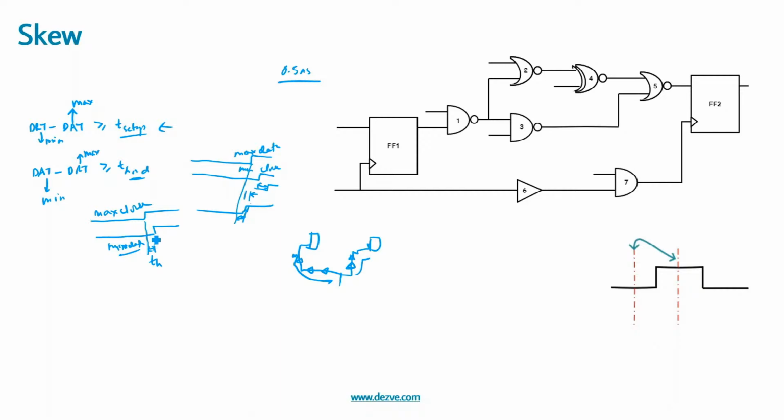Now in this case, where do you want to add the skew, or subtract the skew, whatever be the case? If you see, the worst case would be that we want to narrow this dimension, correct? We want to do this. So in this case we will add the skew so that the clock comes slightly later, so that the margin of the hold requirement becomes more constrained. And in case of hold, you will see that the skew value is getting added to the clock path, the data required time path, and then those resultant edges are compared for the hold analysis.